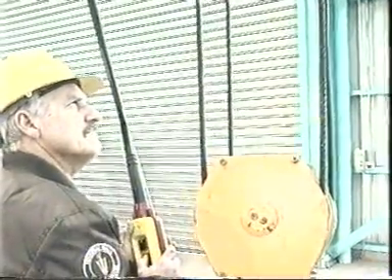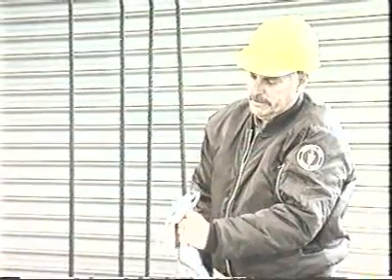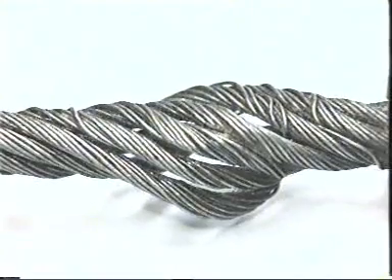Hoisting rope should be the correct size, type and construction as specified by the crane manufacturer. Make sure you know the loading capacity of the hoist ropes which you're working with. Ropes, sheaves and drums should be inspected regularly for wear, damage and corrosion. Frayed ropes can be quickly identified by wiping a rag up and down the rope. If you notice any broken or damaged strands, then inform your supervisor and maintenance personnel.